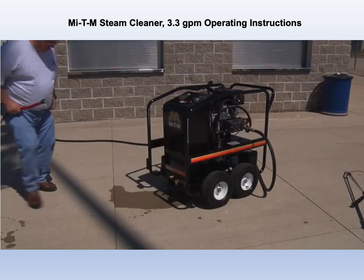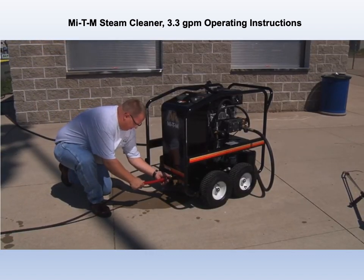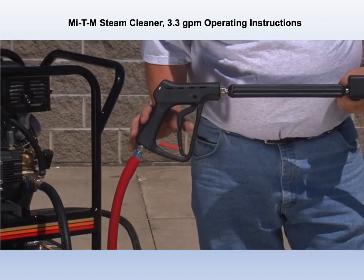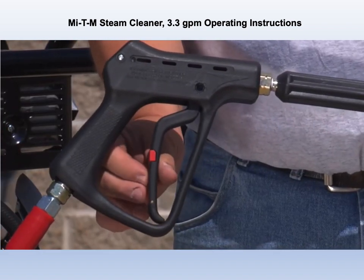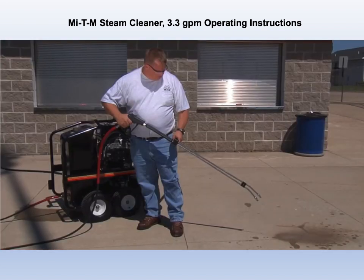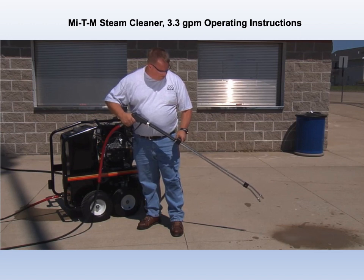Next, connect the male end of the high pressure hose that comes with the unit into the coil outlet on the pressure washer. Be sure the trigger gun is in the locked off position. Turn on the water and move the trigger gun lock to the on position. Squeeze the trigger on the gun to purge the system of excess air before starting the unit. Now you are ready to start the pressure washer.